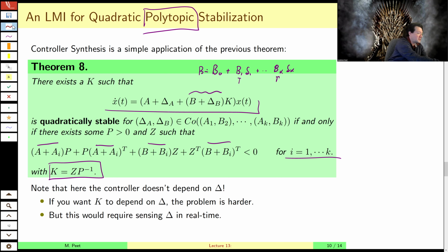And that's important because this is a quadratic stability result, and so it allows the parameter to be time varying. I have a little caveat here, which says that note that because this one controller and this one Lyapunov function are holding for every value of the uncertainty set, like all quadratic stability results, it's a bit conservative, especially if the parameter is not time varying.